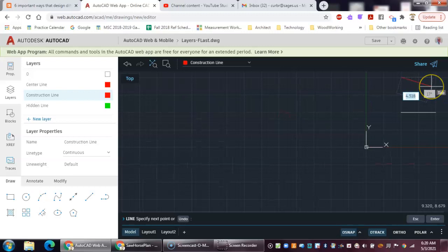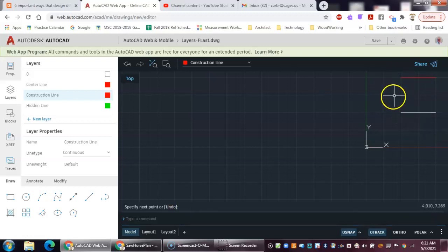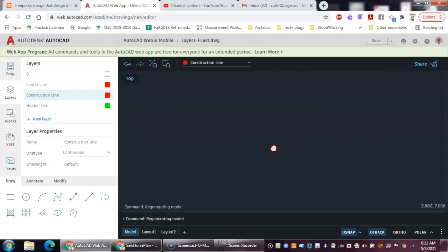Sometimes your screen goes crazy on you. So we're way up over here. I'm just going to draw this line and then we'll get it back centered up. So I'm going to enter 5 for the line length. Since I'm not at 0 degrees right now, I'm showing 2 degrees, I'm going to tab over, hit 0, and hit enter to place that line. And again, notice I'm still in the line command. So right click confirm to exit out, and I will press down on my roller button.